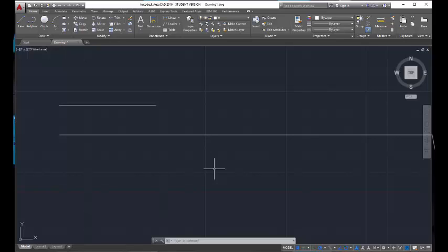And this can be very frustrating for people who are new to CAD because you don't understand what exactly is happening. Now remember that in model space you are building objects that represent real sizes, but we're still working in a virtual environment. So you're going to need to be able to zoom in and out of your drawings, and you're going to have to move around on the screen a little bit as well. So the solutions that CAD came up with for this exact problem are the pan and zoom commands.